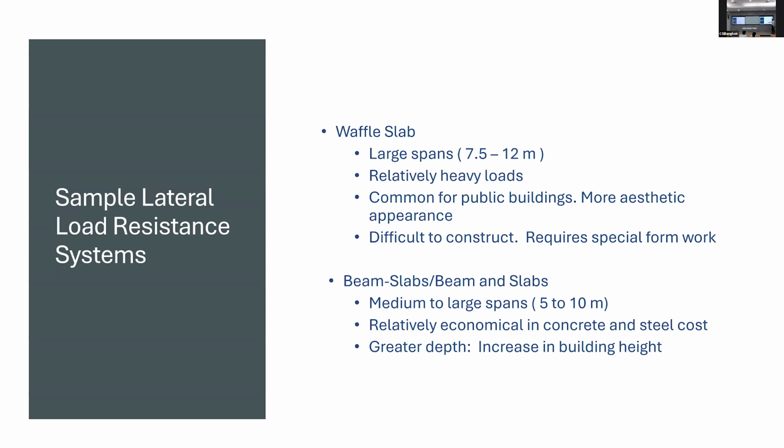Medium to large spans, relatively economical in concrete and steel cost, but greater depth, increased building height. So there are other reasons why people will not allow you. These days, for tall buildings, hardly anybody will allow you to use beam slab. You will find it very rare now, except when people really want to make a very economical building, height limit is not a problem, it's a residential building, and they can put in a false ceiling, or they don't mind the beams. Cost-wise, pure structural cost, beam slab or beam and slab is still cheaper than other systems.